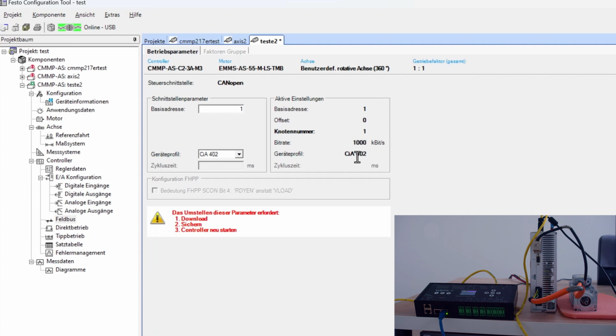So here you have to enable the FCT and also that the motor is online. Here we have our reference. So here you can use jog forward and backward, so that you can see the speed if this is available for what you need. So basically here is the velocity. And here we have one reference. Okay, here the motor is turning. I stop it. You can save it permanently. Okay, this requires a download. So you download the project data. This is downloaded to your device, but it's not secured in the EEPROM. Here is the EEPROM. Here we select the EEPROM.